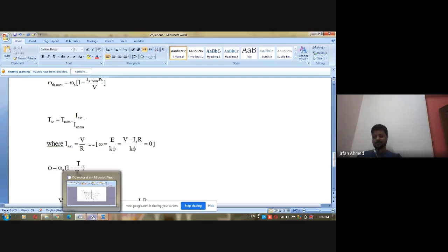No. The answer is: the nominal resistance of a DC motor is defined as the resistance which limits the armature current to its rated value when the armature is locked and rated voltage is applied to the motor.